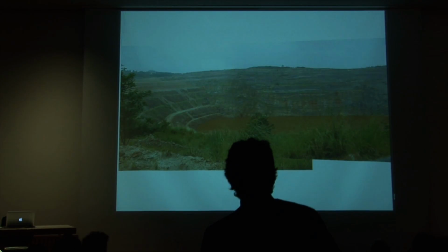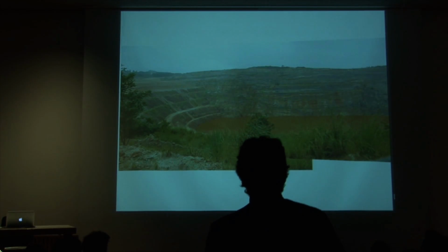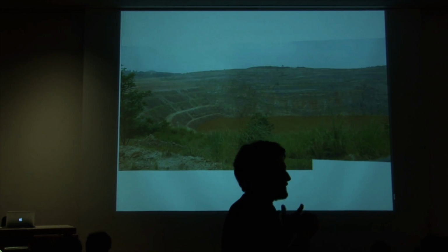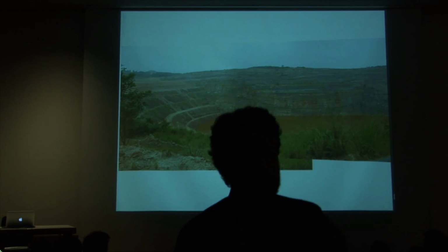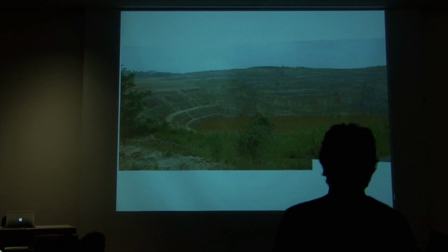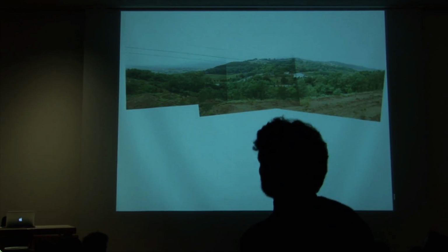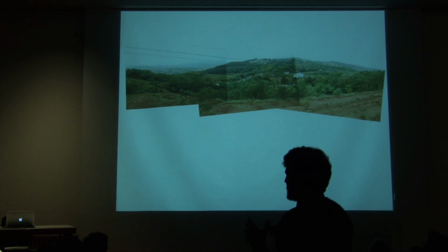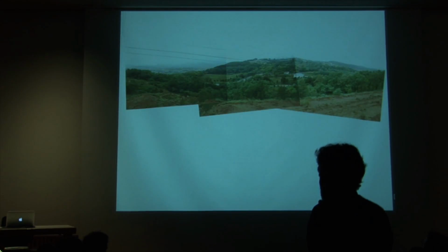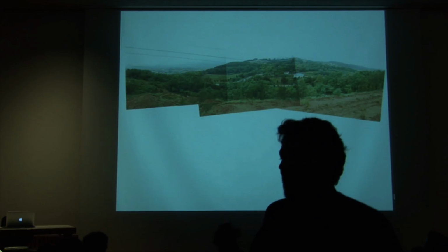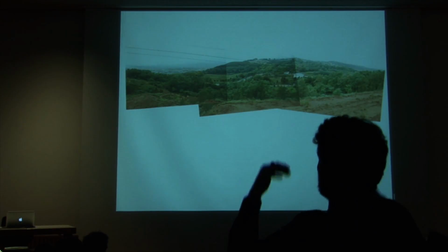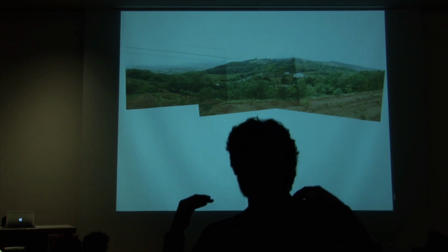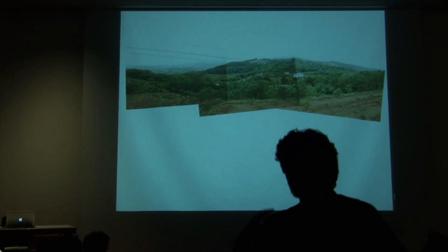All the volume of earth that has been removed from here has been treated, has been filtered, and so the valuable materials or metals have been removed, and this waste has been placed in another position right here, and they have created an artificial mountain. And this artificial mountain is exactly next to our site. So we thought it was quite unsafe to build next to this unstable hill, because with the rain, with the years, it could be eroded, it could fall, the earth could move.